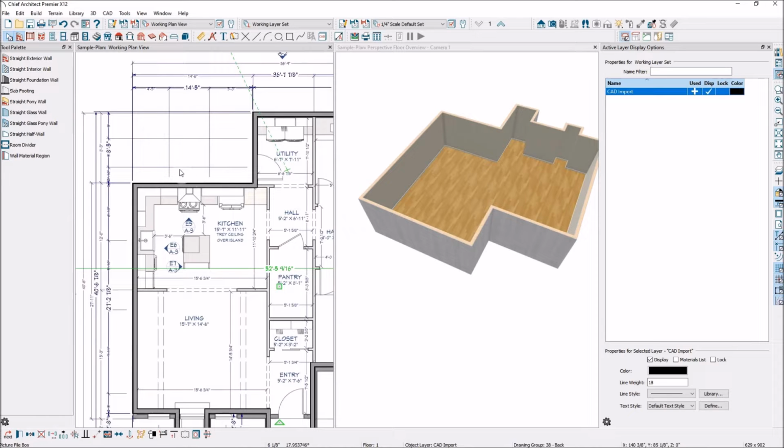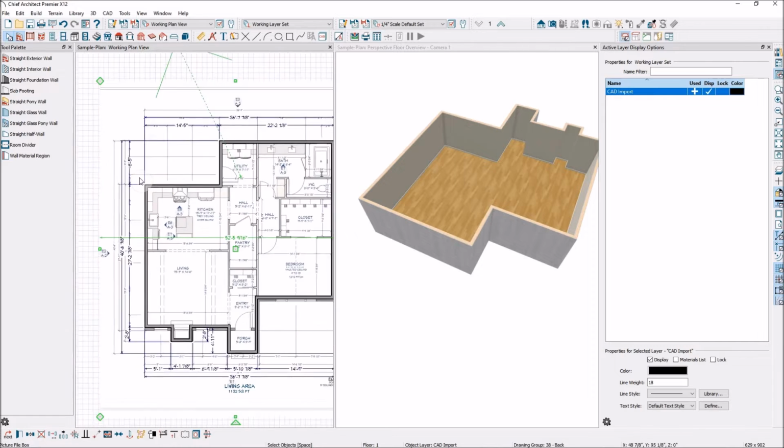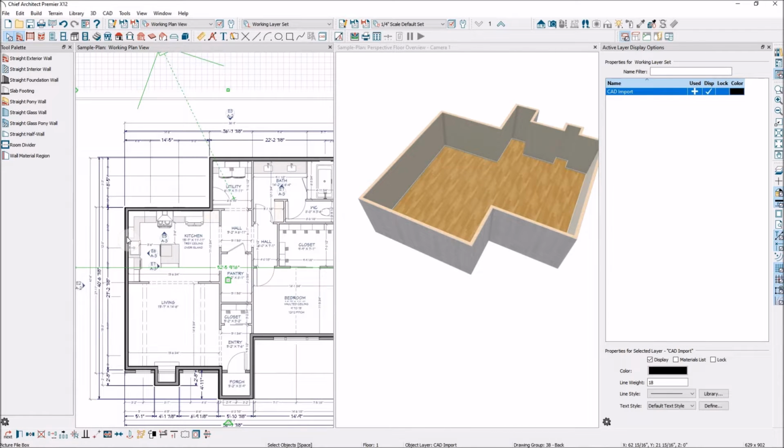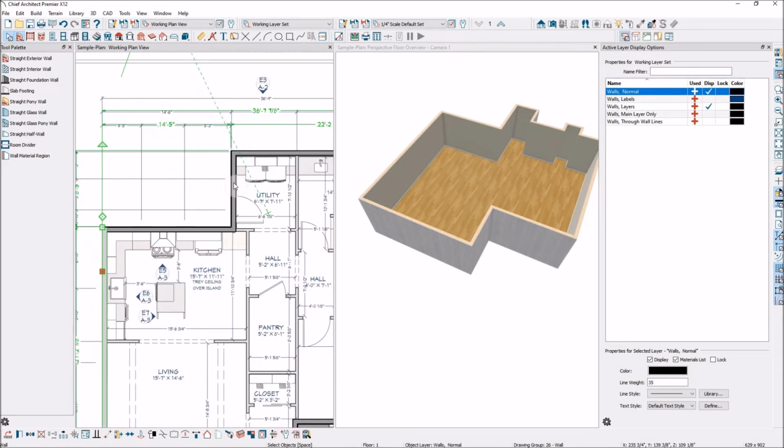So I'm going to start in this corner and work my way around to get these dimensions to match. I'm not going to move this wall. I'm going to start with this wall, assuming this wall is in the right place, but I'm going to move this wall. So you can see the dimension on my image is 14'6", and I want that to be 14'5". So I'm going to change that to 14'5". There we go.